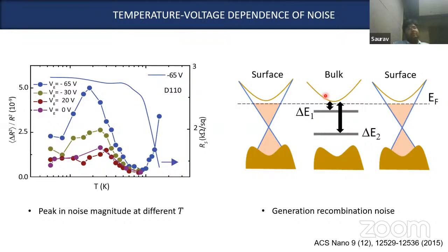So the best way experimentally, yeah, sure. No, no. So we first check the spectrum and we integrate it over a bandwidth where for all the data points it is 1 over f. We first see the spectrum. We choose a window where the 1 over f window is consistently maintained throughout the entire temperature range.